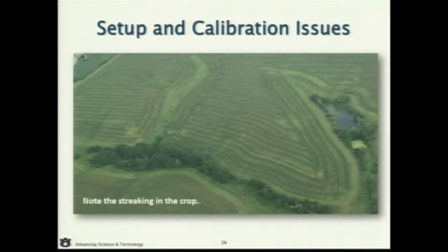We're going to just talk about one in particular, and then talk about rate control in terms of how long it takes. But the first thing is, let's just make sure that we're checking that applicator. This is a variable rate nitrogen side dress unit. You can see that there was some issues just based on the picture and the streaking that occurred. But that setup and just checking and getting off and checking every nozzle, that you don't have any plugs, things like that on a row is very important, or this is going to happen to you.